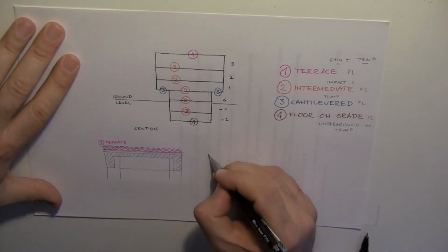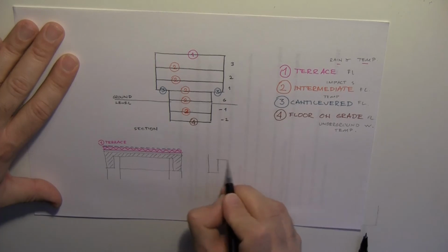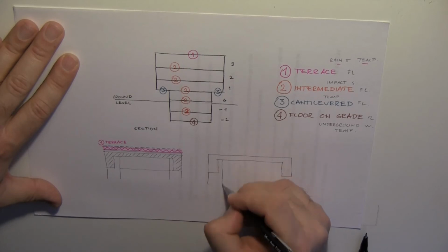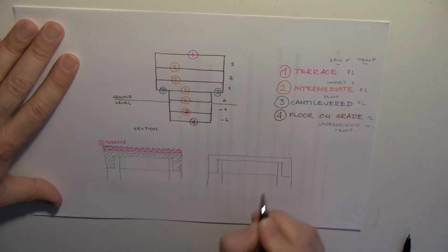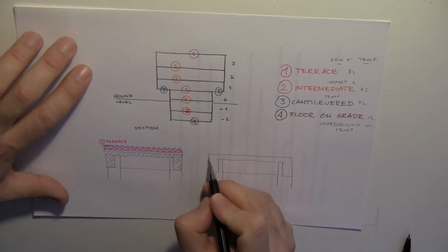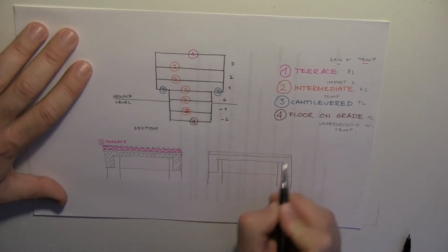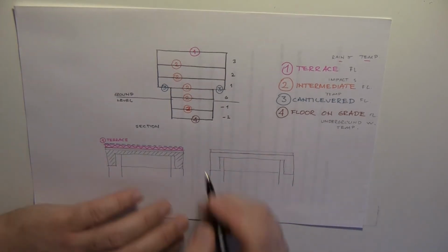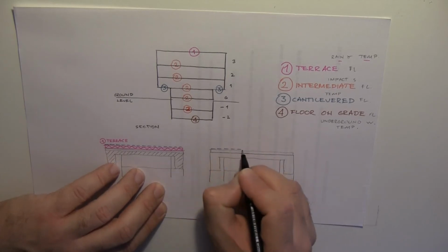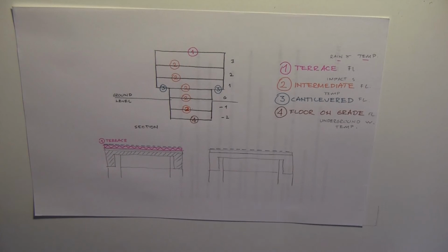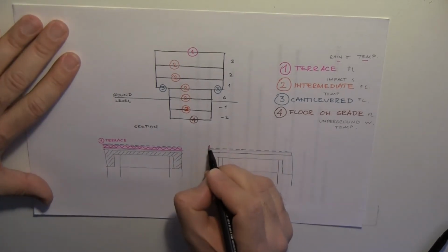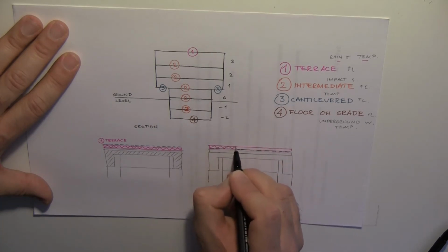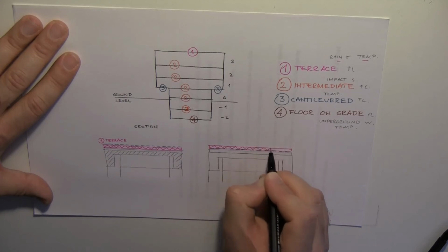Or alternatively, what you can do is you can have your floor, again like this and like that. This is again a terrace floor. You cast screed this time here, and with those screeds you give a slope, so they can be called a slope screed as well. And what you can do is you can place your waterproofing here this time, and you can cover your waterproofing with a thermal insulation. And we are going to call these types of roofs, these types of terrace floors, inverted terrace floors.